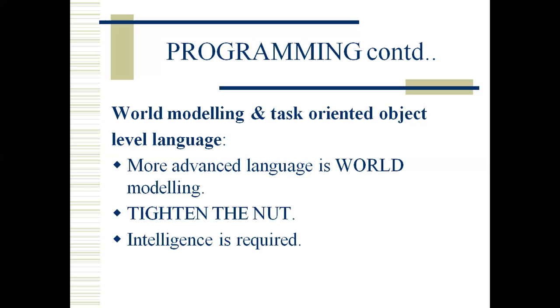So basically, it will act as an electrical power supply, and when the solenoid has been energized, in the sense the electrical power supply has been initiated, that supply will actuate the hydraulic or pneumatic strategy by operating this directional control valve, and that will guide the actuator to rotate in the clockwise or counterclockwise direction as per the switches that have been given.